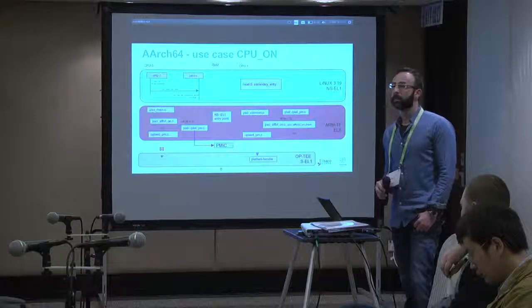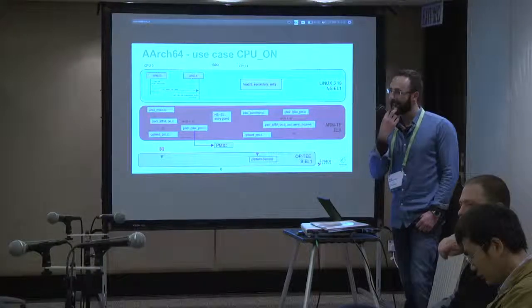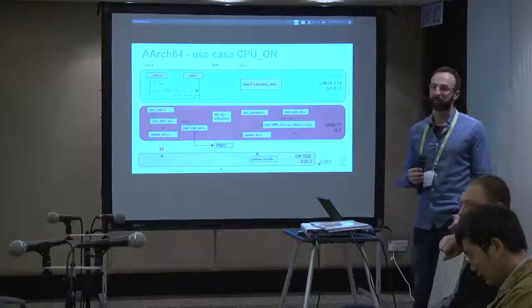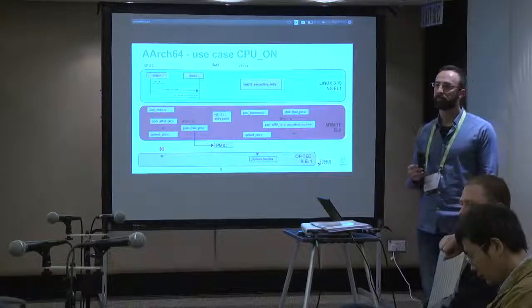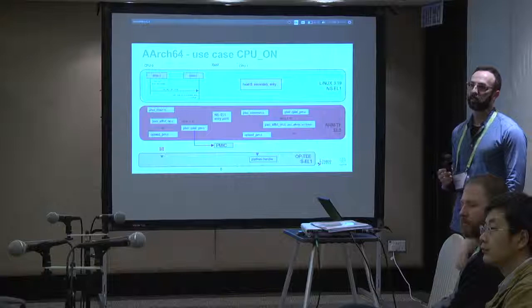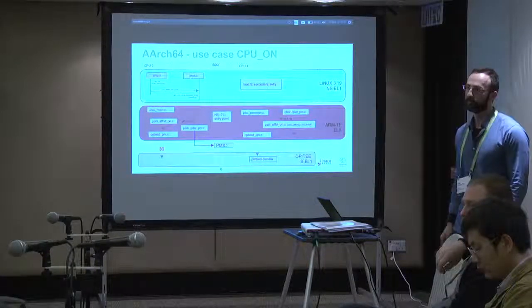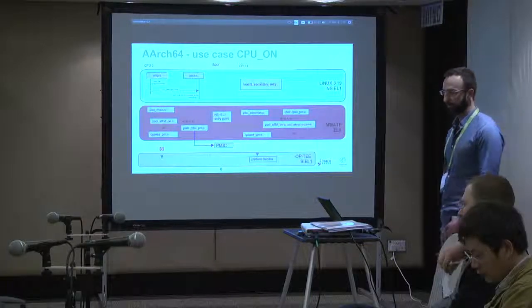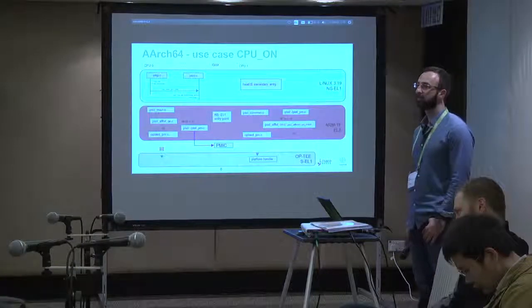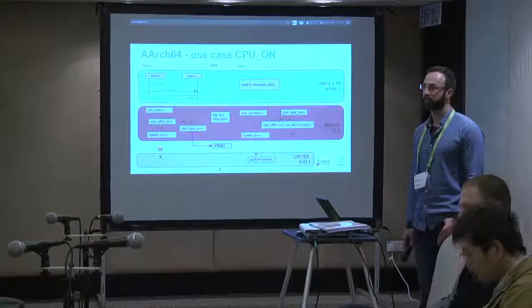It's outside the CPU. So my question is, if PMIC is outside of the CPU, then Trusted Firmware will need to implement some interfaces to access this. It depends if it's on the SoC or off the SoC. On the SoC, it's just memory map. But I guess the question is, what if it's an I2C, and then you have to reinvent the entire I2C driver that's in the kernel, again in the firmware?